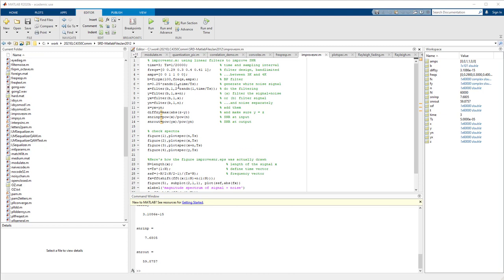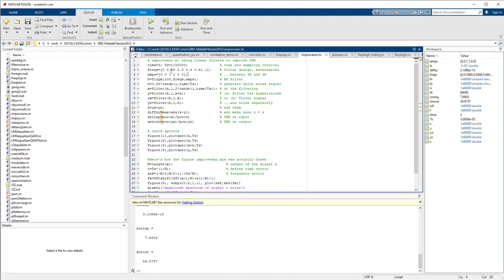We have a filter. The filter is designed as a bandpass filter. So the filter is at the frequency 0.29, we have a rising edge. From 0.29 to 0.3 is the transition from 0 to 1. And then the passband is 0.3 to 0.4. That's all 1. And then from 0.4 to 0.41, that's the falling edge. That's my range for the falling frequency. And then 0.41 to 1 is my stop band, 0. So this is a bandpass filter.